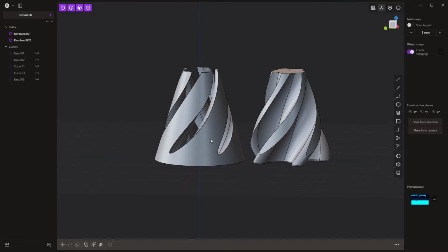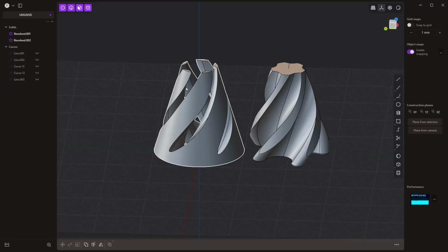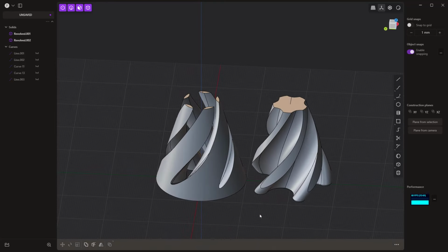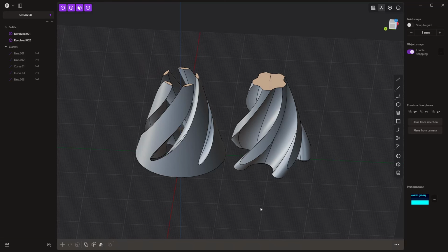Based on your print settings, you may find that you get a lot of stringing happening between these two. You may need to refine some settings a bit, or try print in place and see if you can print it together. But what I've found is that even when we have a good enough gap between these two, even though we make the angle not quite as steep, the bottom edges tend to need a little bit of work. You'll have to move these pieces together in and out just to clean it up a little bit. So make sure that you understand that if you print in place, they may be permanently stuck together. You may have a hard time getting them out. But with only doing a 180-degree twist on here, it'll be a little bit easier. And the settings that we use, that 0.4 millimeters, should give us plenty as well.